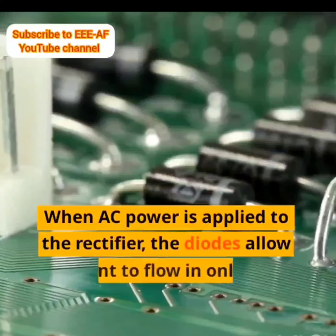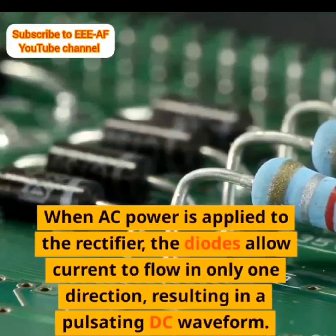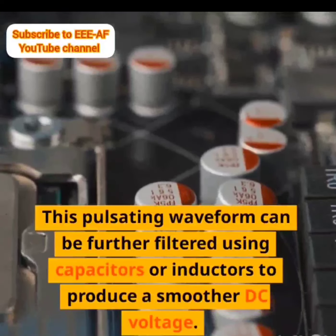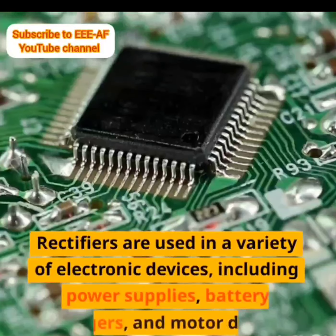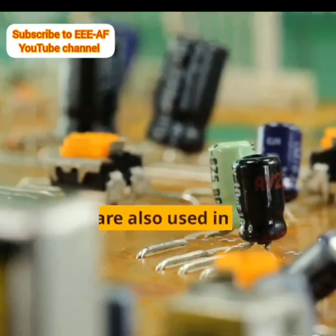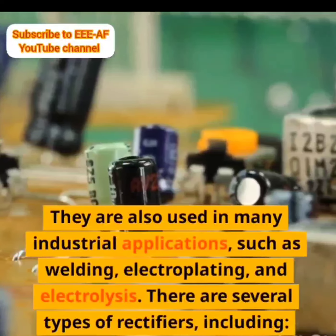When AC power is applied to the rectifier, the diodes allow current to flow in only one direction, resulting in a pulsating DC waveform. This pulsating waveform can be further filtered using capacitors or inductors to produce a smoother DC voltage. Rectifiers are used in a variety of electronic devices, including power supplies, battery chargers, and motor drives. They are also used in many industrial applications, such as welding, electroplating, and electrolysis.